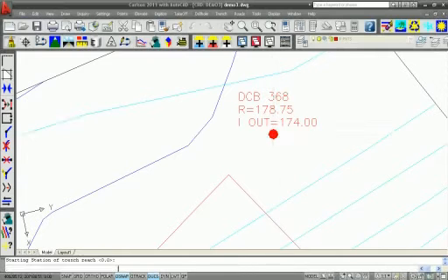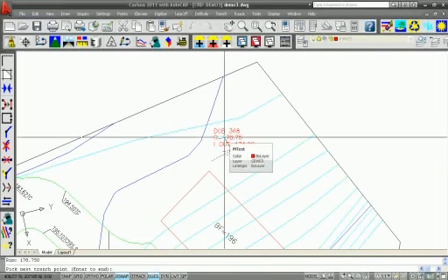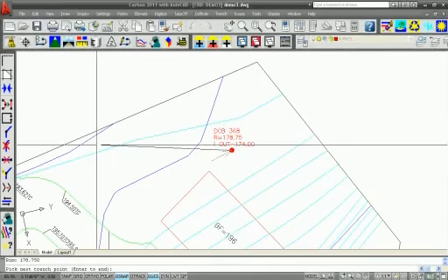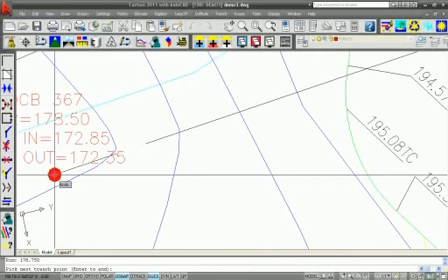Starting station 0, and down here on the bottom, it's going to be the same prompting as you're used to if you're entering in a polyline. So select text of the manhole ID. The invert in, this is my first one, so it's going to be the same as my invert out. And then the rim elevation. Okay? And now it says pick the next point. So I can pick any point here on the drawing, and I want to go to my next manhole here and left click.